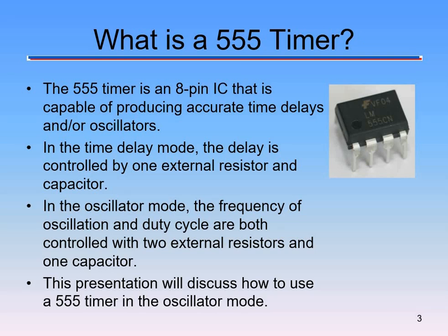Remember, oscillation in signal analysis is a signal that's going up and down, so we had our square waves or our sine waves and things like that. We can control the time delay with a combination of resistors and capacitors. They're called RC circuits. There are also RLC circuits, with resistor, capacitor, and inductor, but we're not going to get into those yet. That's an advanced course that you can take with me. But an RC circuit is how we can control oscillation.